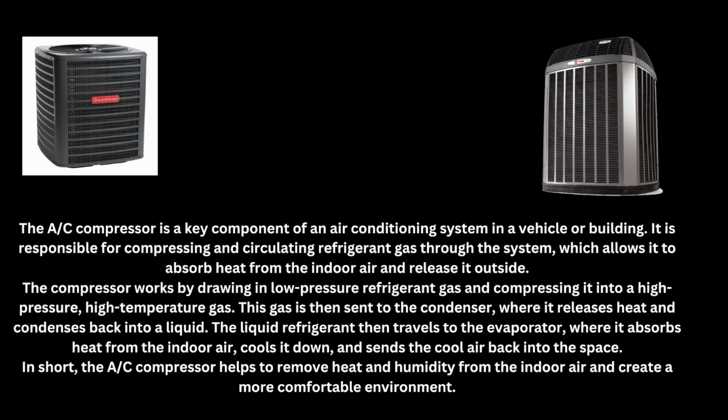It increases its pressure, and then the gas is sent to the condenser where it releases its heat and condenses back into a liquid. The liquid refrigerant then travels to the evaporator where it absorbs heat from the indoor air, cools it down, and sends the cooler air back to the space. In short, the AC compressor helps remove heat and humidity from the indoor air and creates a more comfortable environment.